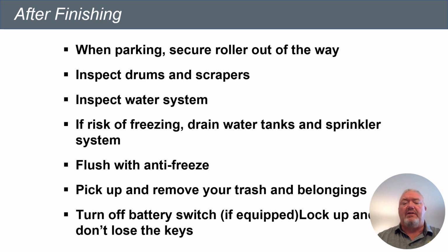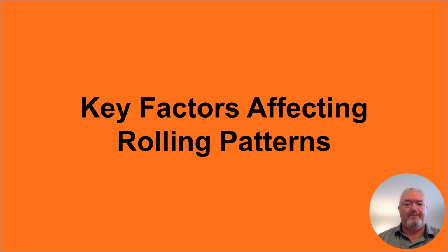Older machines had a manual battery disconnect switch. The newer ones do not, because we have the DEF fluid. When you turn the key off, the DEF fluid pump pulls all that material back through the lines, back into the tank, so it doesn't crystallize in the lines and derate the engine when you least expect it.